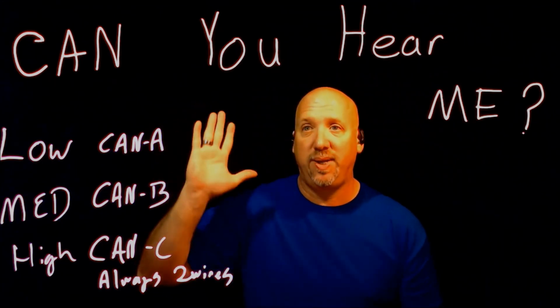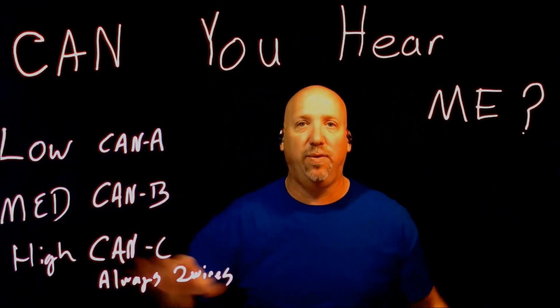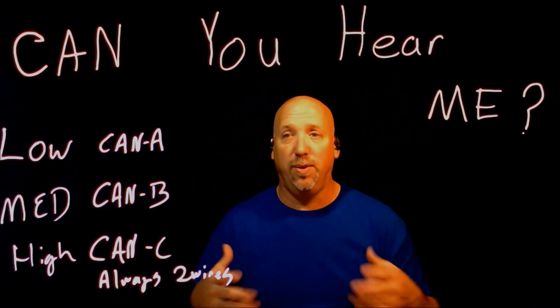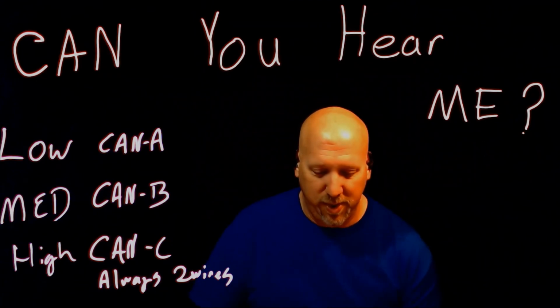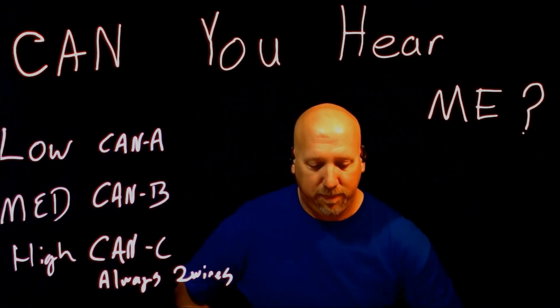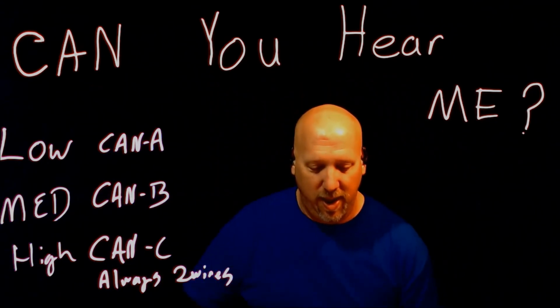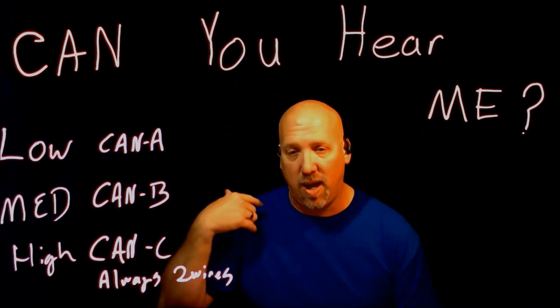Or if a student says, I have a problem with this, that's a priority message, then they can talk back and forth. All the other modules or students can sit there and listen in and see what's going on, but it doesn't really affect them most of the time. The originating module will keep resending the message until it's completely received. So just be aware that even a low priority message can be lost. The high priority messages will be sent until they are received and acknowledged.